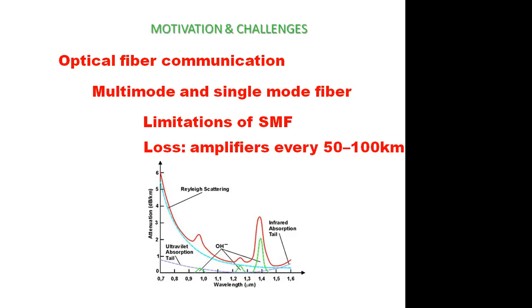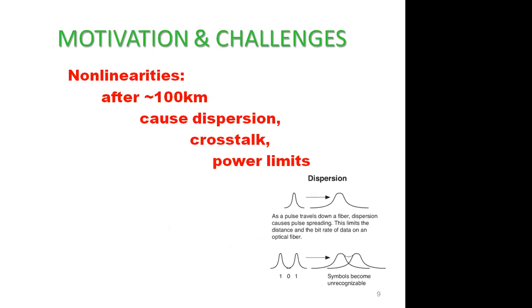Then the second one is dispersion, right? Someone is saying loss, but loss is something different from dispersion. Okay, there is one more term that comes into optical fiber known as non-linearities. Keeping the fiber core area at 12 micron, I want to pump more power. I'll keep 12 micron only and pump more power. That may be the solution. But if you do that, it will get into non-linearities.